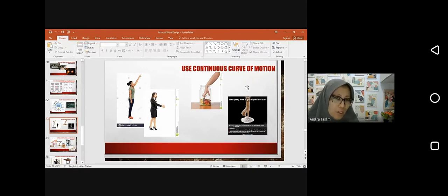If you think of the picture, the very stylish lady taking something from the highest place is okay for one time. But if we talk about an operator whose job is to assemble parts, and the product consists of 50 parts, and 30 of those parts are placed at a higher level, the operator has to reach for them 5 times. So it is not good, I think. It's better if we do a layout and put them in proper positions.